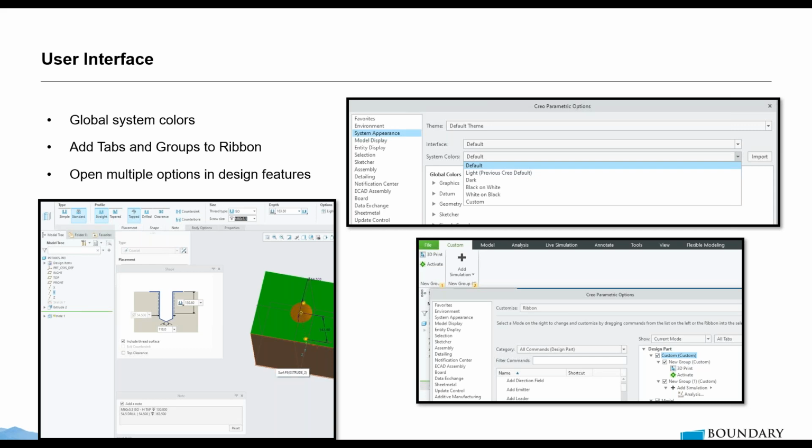So you can customize that, and it's quite easy. One of the new features available in Creo 8 is that you can change your flyouts. For instance, this whole shape, you can see normally it would be here at the top. So here I'm showing my placement, I'm showing the shape, and I'm showing my notes. In Creo 8, you can move these flyouts around.